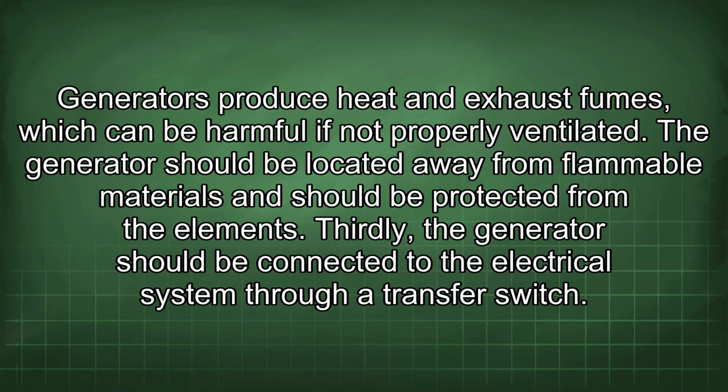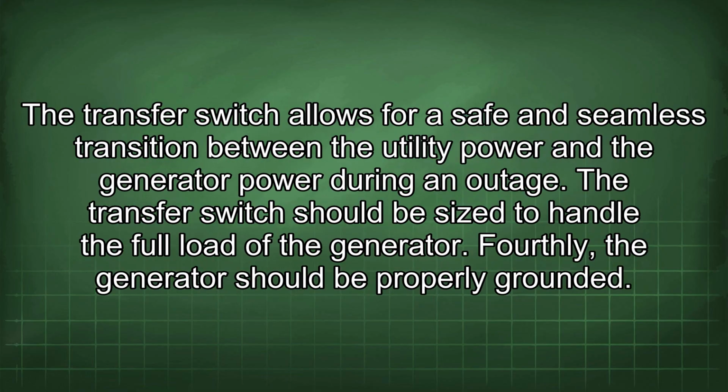Thirdly, the generator should be connected to the electrical system through a transfer switch. The transfer switch allows for a safe and seamless transition between the utility power and the generator power during an outage. The transfer switch should be sized to handle the full load of the generator.